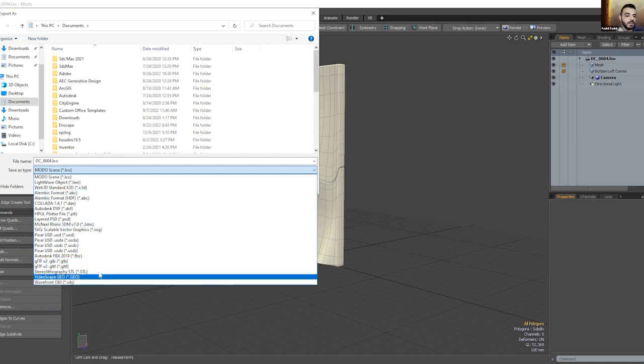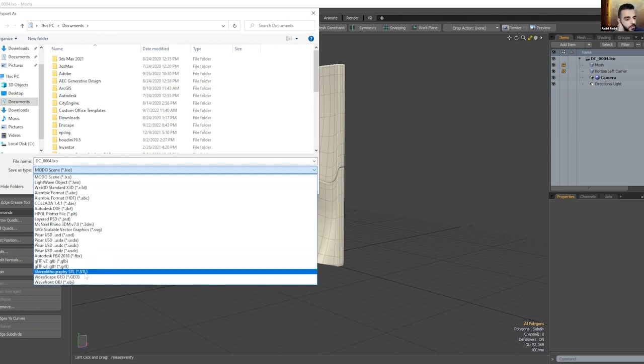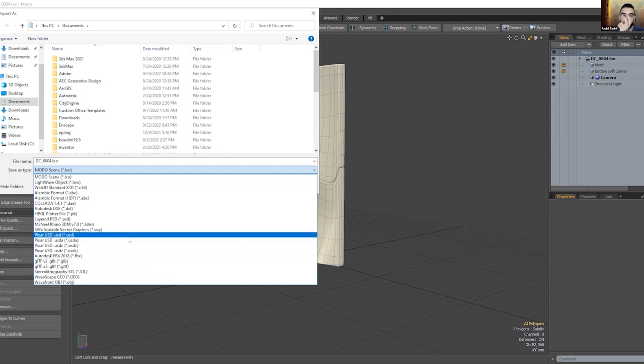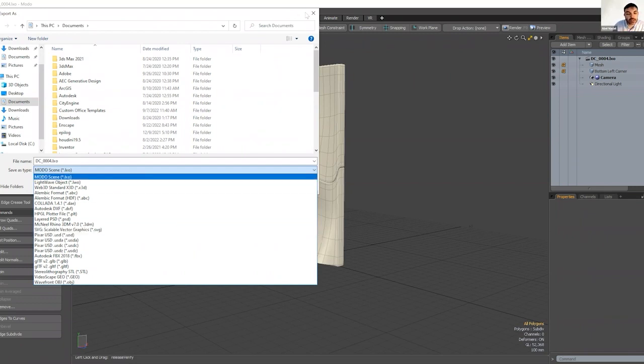I mean, even STL, we'll bring it. You can definitely bring it as a point object, and you can always bring it as a mass to sort of tell Revit that it's a wall, and then go from there. Put a category, put in a template, and add a category. Oh, that's excellent. Okay, cool.